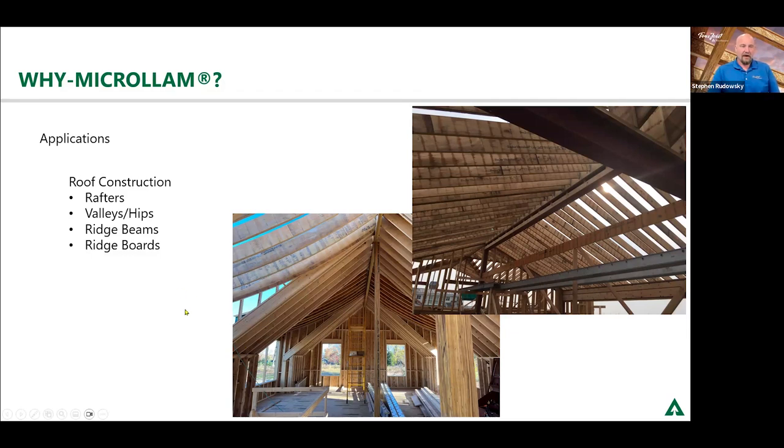For those of you that are on from engineering and architecture, even framers, remember that hips and valleys are always considered structural. They're going to be taking weight. So another application, 1.75 inch, are going to solve quite a few of your hip and valley areas.